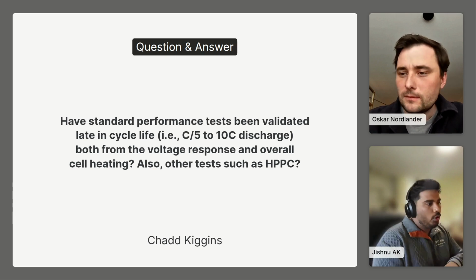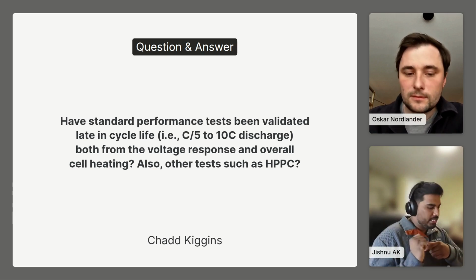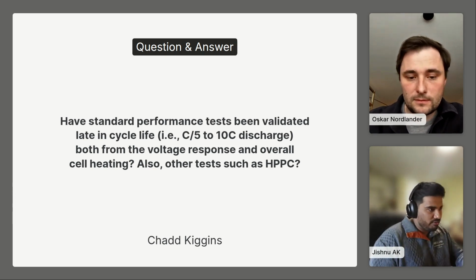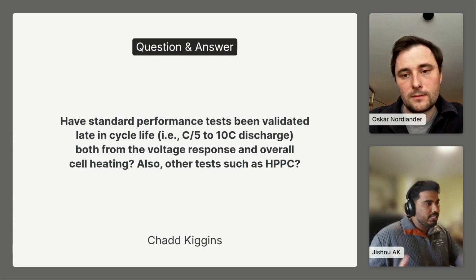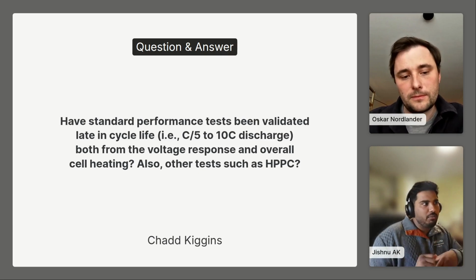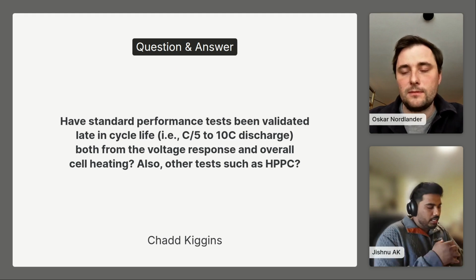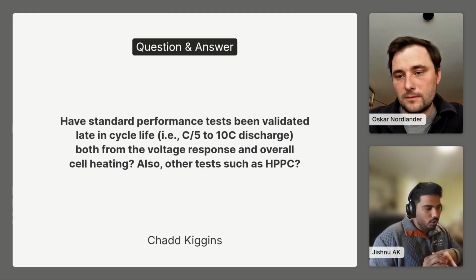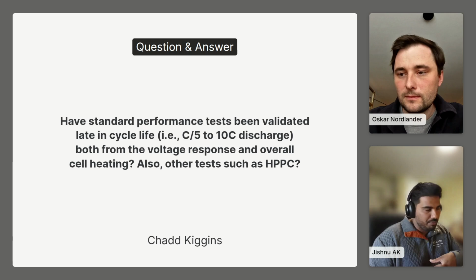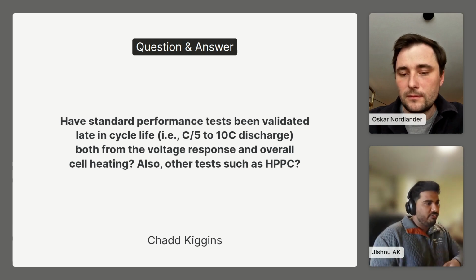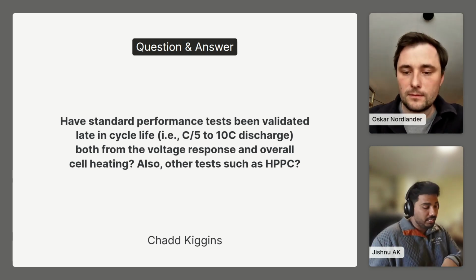So, at the moment, we do an extensive electrochemical validation at beginning of life, and at later phases we only validate across some of the CC datasets that we have. For the aging study shown before, we validated on voltage response of C/3 and 1C. We don't do an extensive validation at later phase. This is something that can be done.